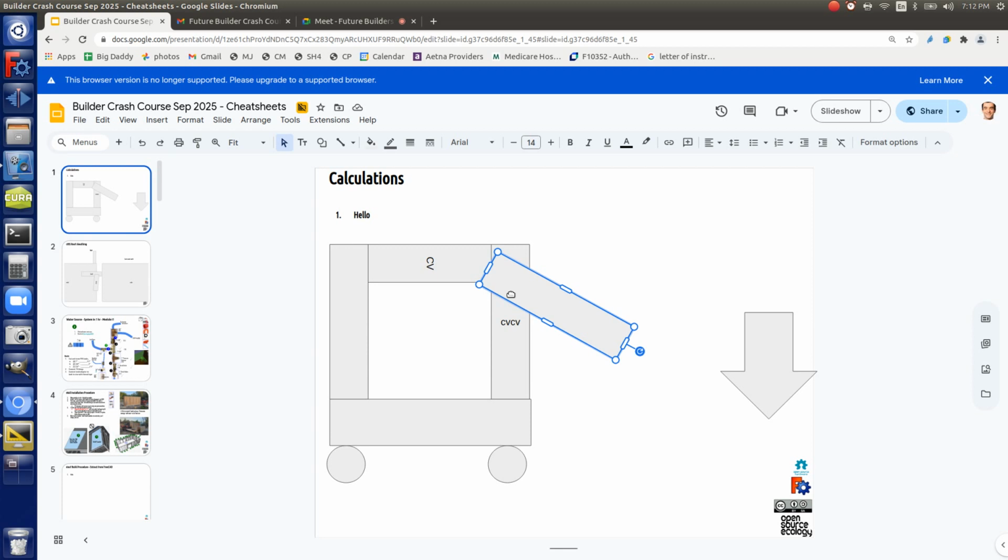How hard did you hit that tree? If we're talking about 7,000 for a standard load, impact shocks are typically, the rough hand-waving figure that engineers use is 10x. So you're designing not just for that weight of 7,000. Say you get into accidents and hit things, or you're going fast down a road and hit a bad bump. Those impact impulses typically add a 10x factor to what you need to solve for.